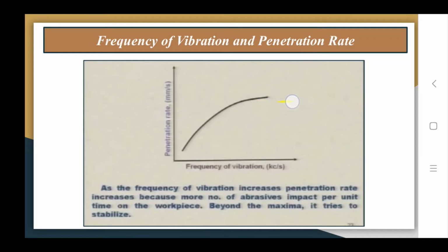So as the frequency of vibration increases, the penetration rate increases up to a certain limit, and with more abrasive particles impacting the workpiece per unit time, definitely the penetration rate will increase. Beyond the maxima, it tries to stabilize, as you can see over here.